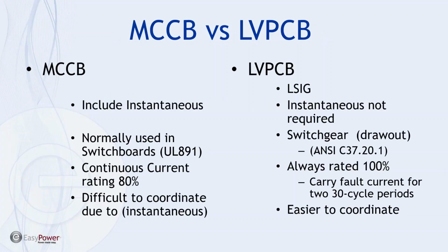Now, the topics of molded case circuit breakers versus low voltage power circuit breakers. It's pretty much understood that because instantaneous trip is included as part of the standard design of a molded case circuit breaker, it's very difficult to coordinate because you have overlapping instantaneous trips. Now, normally, molded case circuit breakers are used in switchboards, which are actually governed, if you will, or stipulated by a different standard than switchgear, which is used for